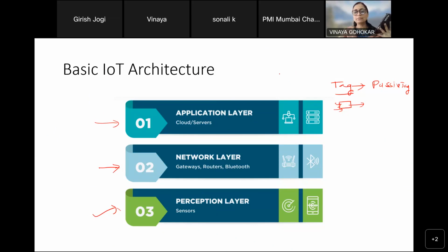Now, when this RFID tag comes in contact with a device called an RFID reader, which is there on the toll booth, the tag gets energy and gets connected to the RFID reader. It transfers the data from the tag to the RFID reader. And further, this RFID reader is connected to internet because your bank account is also connected to your tag. This RFID system is even called EPC, or electronic product code. This deducts the amount from your bank, or the money which you have already deposited in your account, and the system completes the transaction.